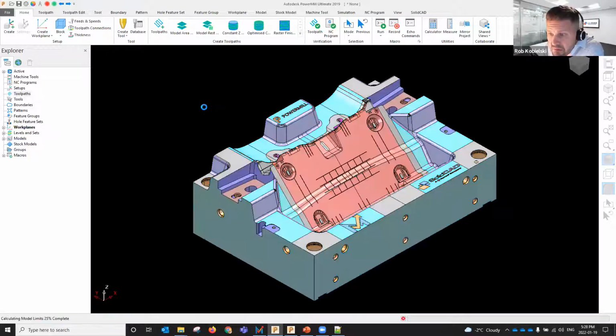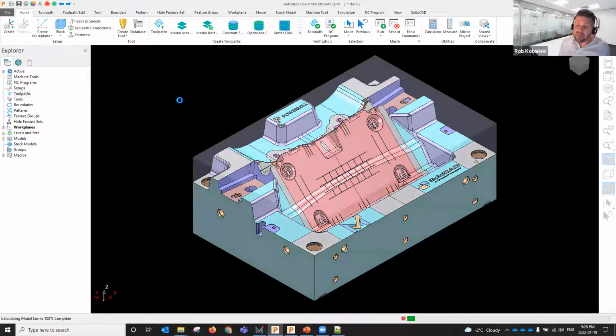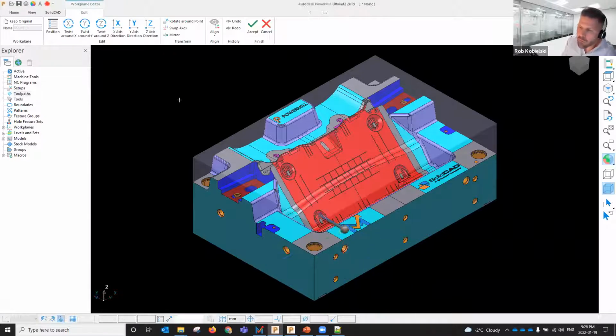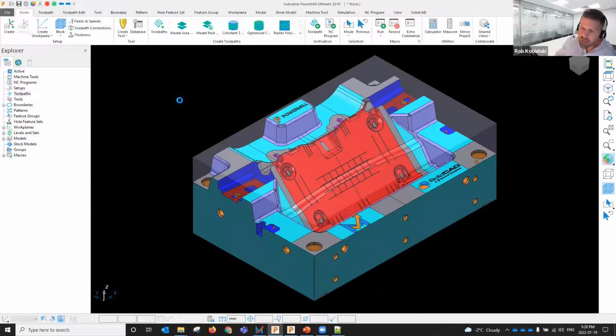Okay. So the first step is just the first couple mouse clicks to say, how do you want to make your stock, right? How do you want to make your raw block size? So you can select the different axes to expand on, key in whatever value you want, make it based on your global transform, specified work plane, or you could even have the option to pause, allow the user to make it manually, and then continue the process.